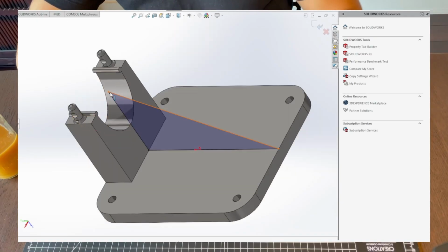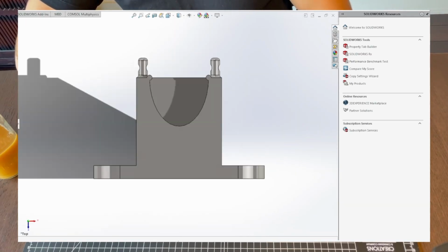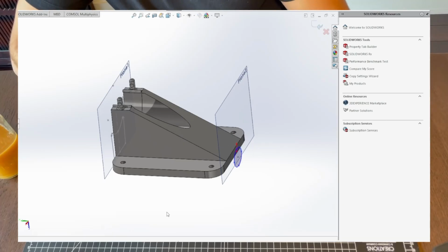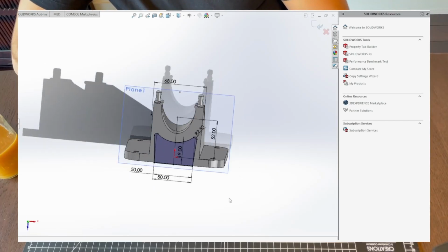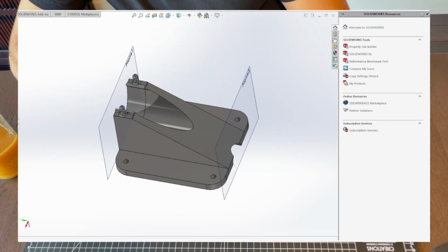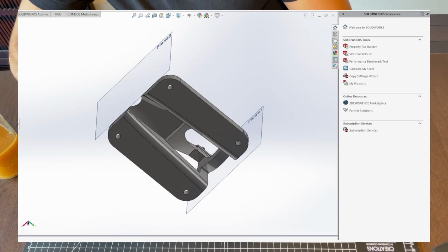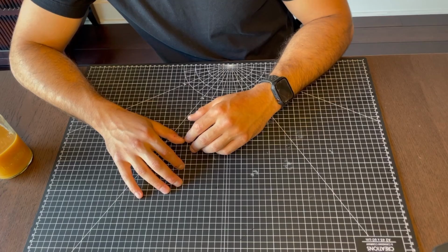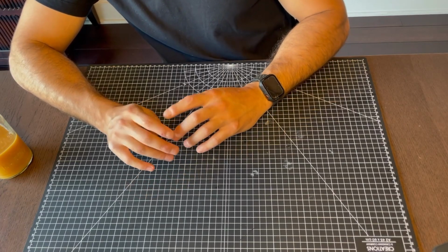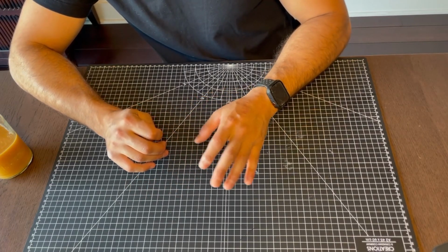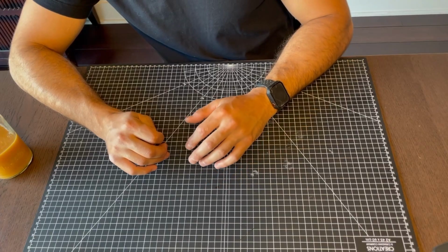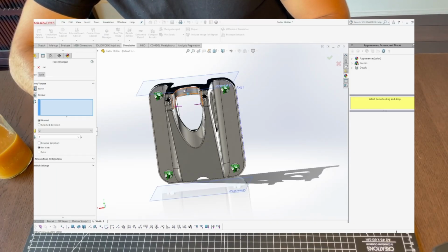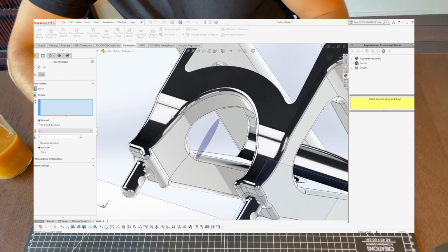I started out by designing the part myself, just based on what I think would make the strongest shape. Obviously, it was a bracket in the beginning, but I also wanted to accommodate the curvature of the guitar, how it's going to be hanging, all of these different details. Next, I whip out the design study toolbox and define some key things. First are the loads. I need to tell the program what areas are going to be carrying the guitar and what direction the guitar will fall towards, pretty much where gravity is.